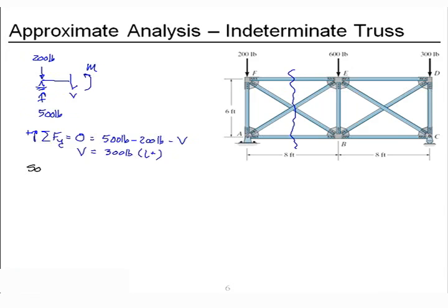All right. So what does that mean for us? Well, let's draw that part we kept. We'll consider the members as well. I have an unknown in each member. I know that the geometry of my diagonals is a 3, 4, 5.